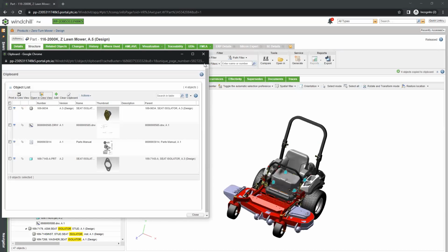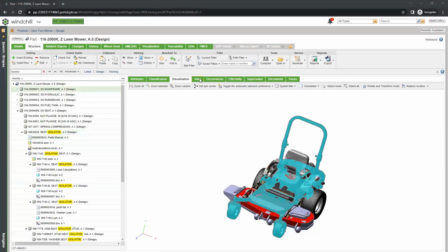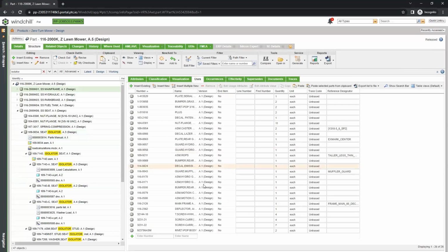And you can also from there add some comments, markups. A lot of people use it to document problems. So whenever they have an issue that comes up, go to Creo View, document the problem, add a comment to that visualization we were just looking at, and then save it to Windchill as a problem, or attach it to a problem report. And then you have a workflow in place that will go through making a change to address that problem. But everyone's looking at that Creo View visualization to understand what the problem is and where it started.